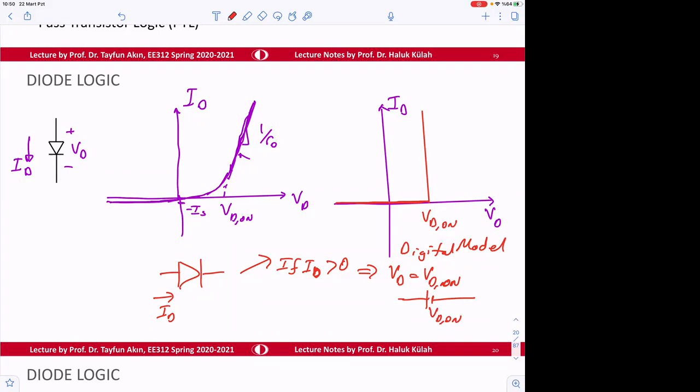So normally, you know, if we had a resistance in here, we could add it. So if the slope was like this, we could add that resistance also, but we don't even care about that. Because for us, this is an element either turning on or turning off. So if VD is less than VD on, we say that ID is equal to 0. So the model becomes like this. So no current is passing through here. So ID is equal to 0.